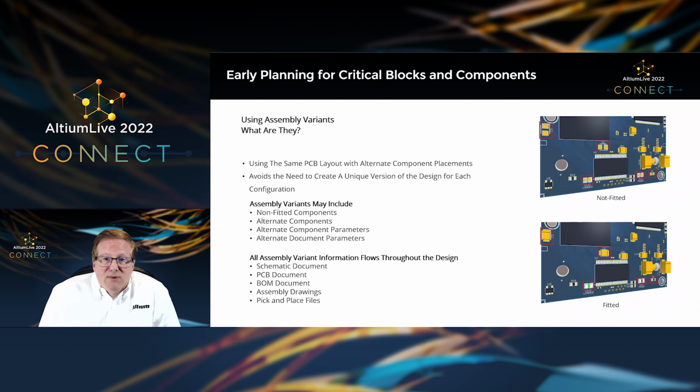Another aspect, and we're starting to enter into the area of Altium Designer here, is the idea of using variants. Well, what are variants? It's basically using the same PCB layout with alternative component placements. Now, what I've spoken about primarily before this point has been more of the design side types of decisions you make. Variants are certainly something you will consider at design time.